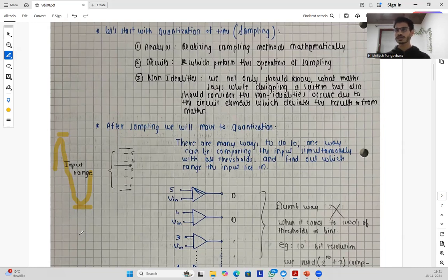So we have 4 bits. So then we have 4 levels, or let's say we have 5 levels. So at this particular amount of time, the value lies between this level or this bin. So basically we have 5 bins going from 1 to 5. So we will then discretize it, that at how many volts is it. So that's how we discretize the amplitude.